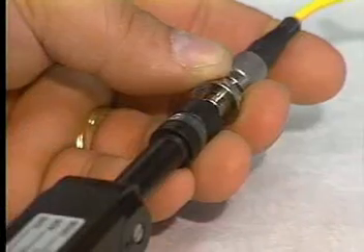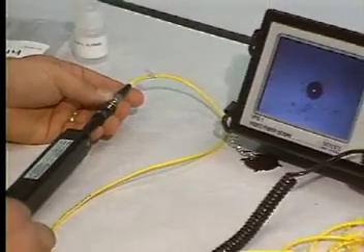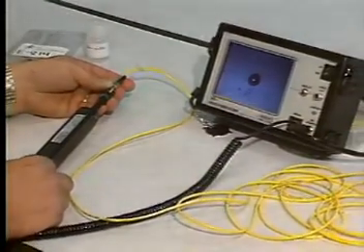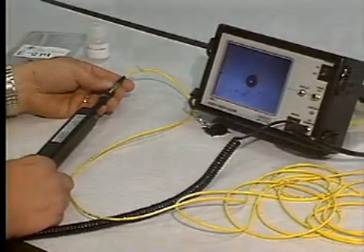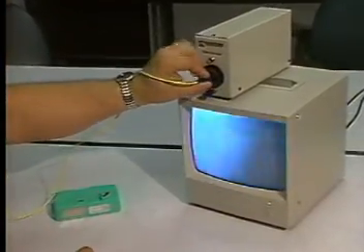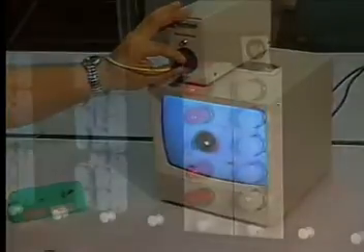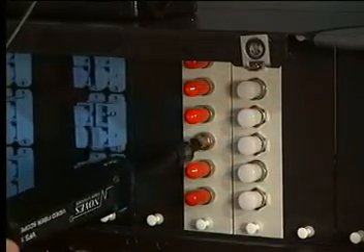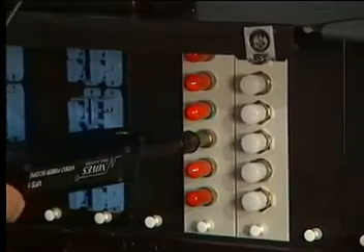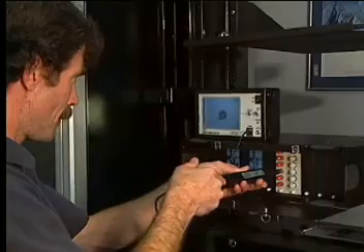There are also a number of video-based inspection scopes available. These scopes can be safer to use than their optical counterparts, as there is no chance for a stray laser beam to enter the eye during their use. There are video scopes designed specifically for examining connector ferrules, as well as scopes that can be inserted in bulkhead connectors found in patch panels or in media outlets. And some scopes can be configured to do both jobs.